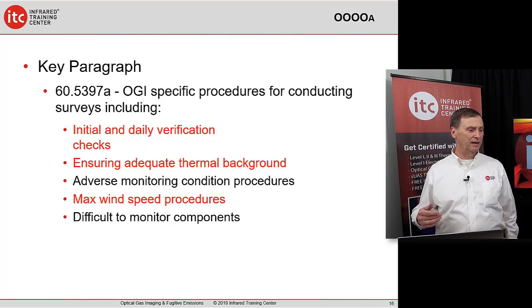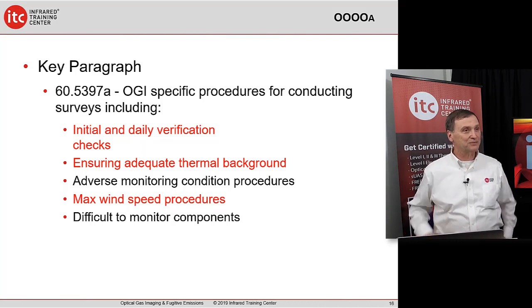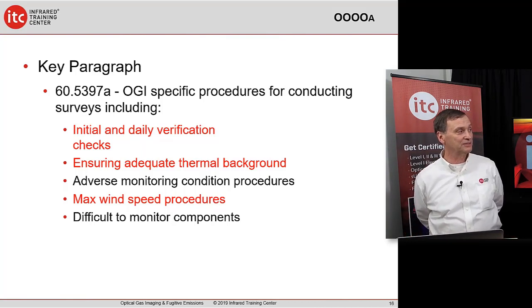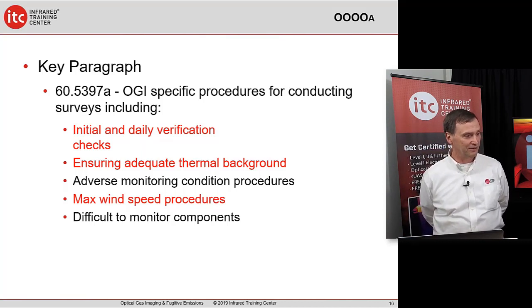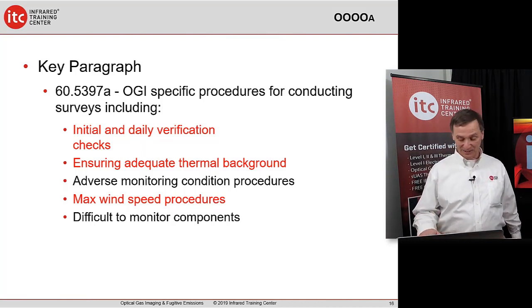But to keep one thing in mind, for all that independent testing, that was done with a 1% diluted gas. So it was 99% nitrogen, 1/2% of propane, 1/2% of natural gas. And so the test was done with a very, very, very dilute gas. And we were able to see it, probably up to, I think, 20 miles an hour leaks. So the cameras are extraordinarily sensitive. And that would be mostly in the high sensitivity mode of the camera. And you don't have 1% diluted gas inside the pipe. You have 100% concentrated gas in the pipe.